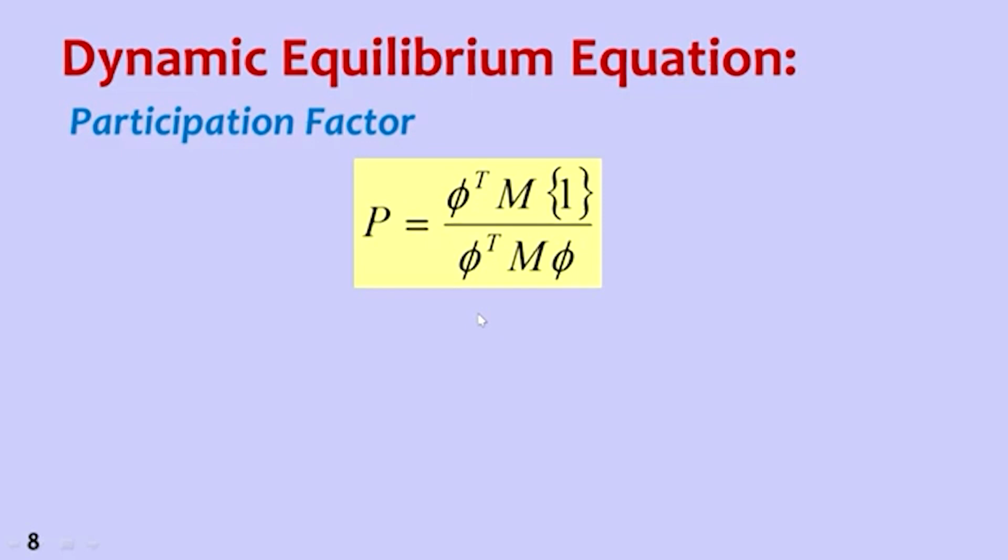So what we do is first mode, second mode, third mode, fourth mode we add. We add mass participation, and if it is crossing, say, 95%, then we stop at that point. So we need not take all the mode shapes into consideration. If we take the first few mode shapes where total mass participation becomes more than 95%, we can do the analysis. So that is what the participation factor is.